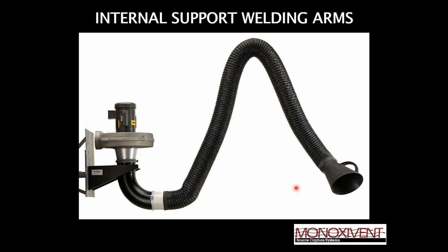This picture that you see is an exact replica of a solution that I used for a Home Depot repair facility, where they had a bunch of benches set up and they were working on small motors, like a weed whacker motor, lawn mowers, things like that. You can take this configuration, pull that handle of the hood and position it right at the exhaust port, and it'll hold the position. In this case, you can see it has a direct mount fan, so it's bringing all that exhaust in, and then it was exhausting right out through a sidewall. So that's just one example.